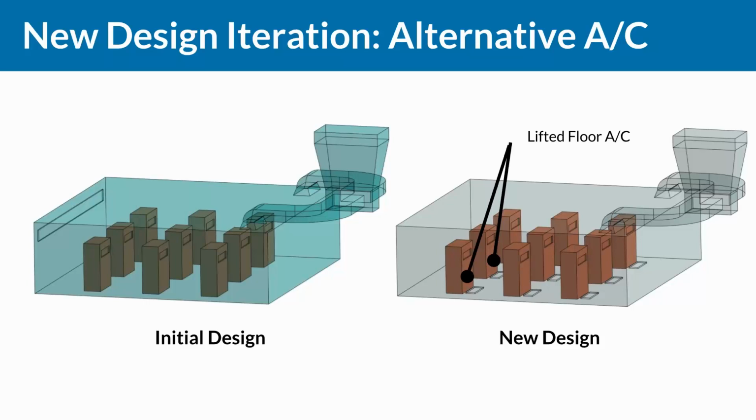And one thing that we have to notice here is that we are using the same flow rate between the two scenarios, or the two designs. So the same quantity of energy that you will spend to create this flow over here will be the same over here. But now let's see the effect of just changing the inlet and creating multiple inlets close to the heat source, and how this will affect our simulation.